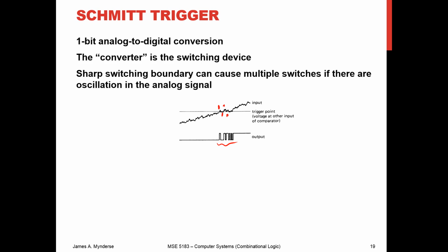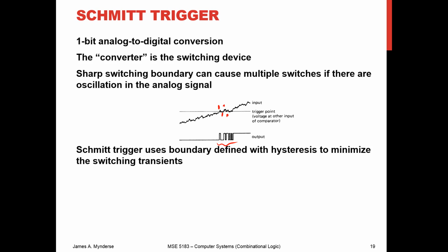And so if we were using that as an input for our combinational logic, we would end up with combinational logic that's bouncing all over the place and could be behaving very badly when you consider propagation delays and if you add in sequential logic. So a Schmitt trigger is useful to add hysteresis. And so hysteresis is something like this, where you've got this gap in these transitions.